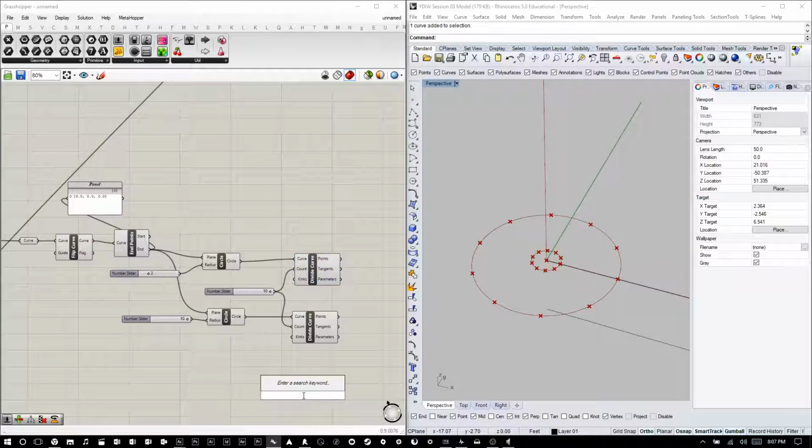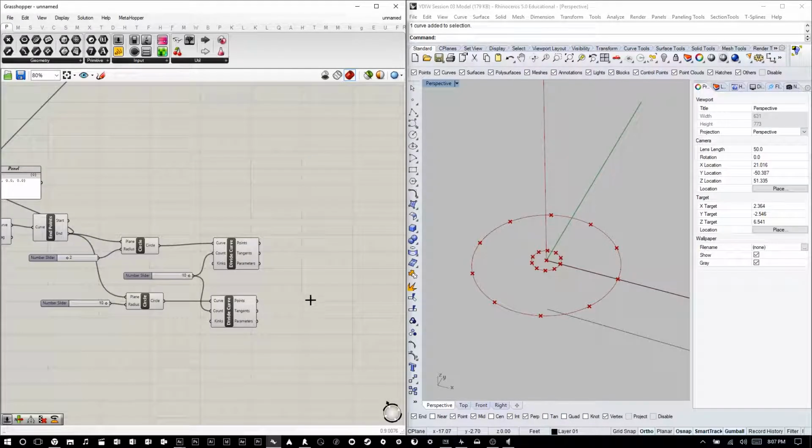I'm actually going to create a surface from my outer curve, and I'm going to trim it by the results that I'll show you in a second. So let's go ahead and create the lines that constitute our spiral stair, and then we'll use those lines to divide a surface into each step. So I'm going to create a line component, wrong line component.